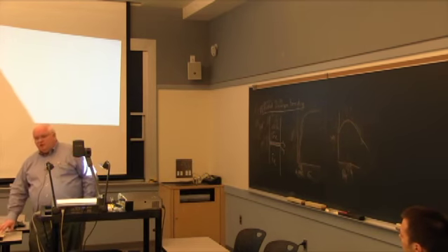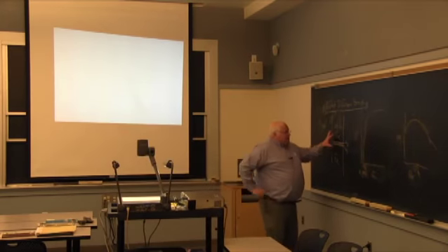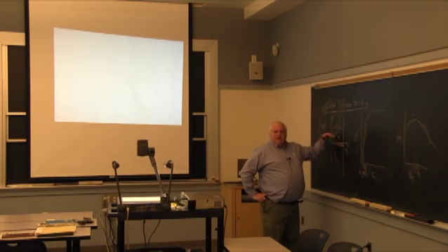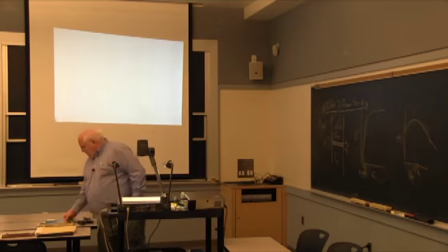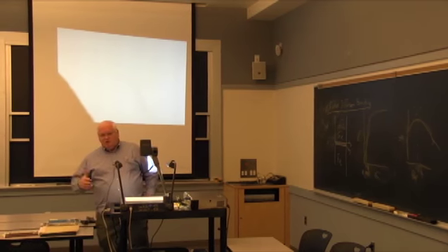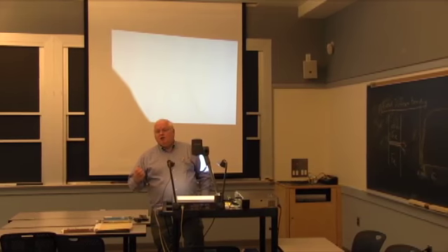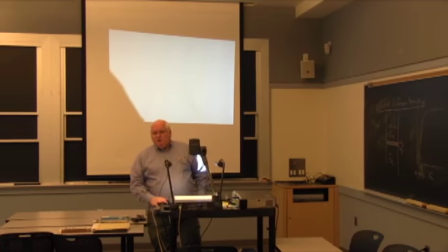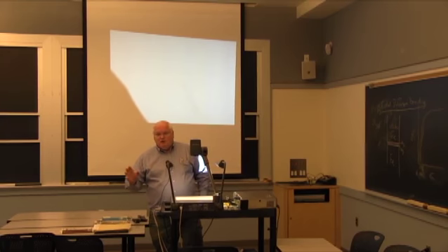And they could be 1/2,000th of an inch, you're electroplating them on, so they can be very thin. They have to be very thin, or you actually have to use enough force that you actually flatten them significantly. But you'll see, actually, it's in some of the notes. I've got some graphs later. It's actually in the brazing manual, and so when I get to brazing is when I usually talk about contact strengthening. But in fact, braze joints can have a 5-fold increase in tensile strength if they're 1/1000th thick as opposed to 5/1000th thick, okay? And it all has to do with this triaxial state of stress you can set up